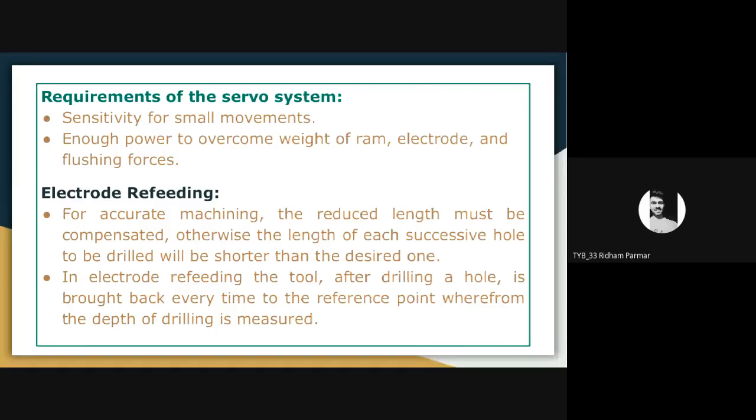Now before refeeding, I will just talk about the servo system also. I will repeat the same point. The servo system is used for the EDM process only. For what purpose? To maintain the predetermined gap between your tool and the workpiece.